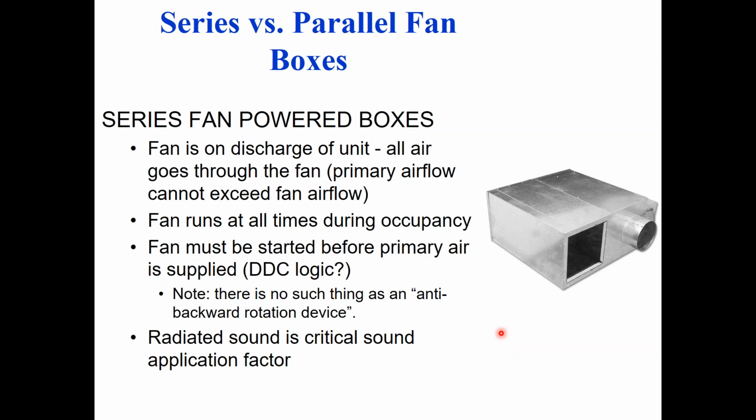If you have DDC controls, those boxes will be in communication with the air handler control, and most of the DDC manufacturers are smart enough to tell all the boxes to turn on first, and then tell the air handler to turn on, and you, the user, don't have to enter two different start times.